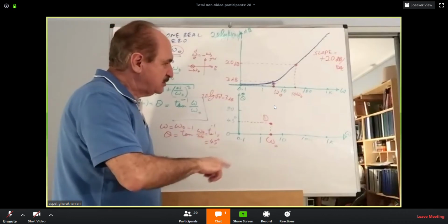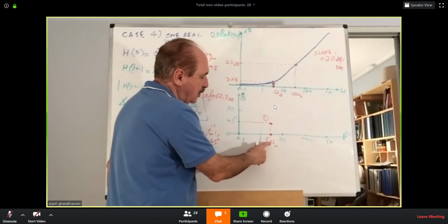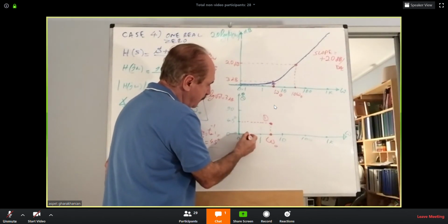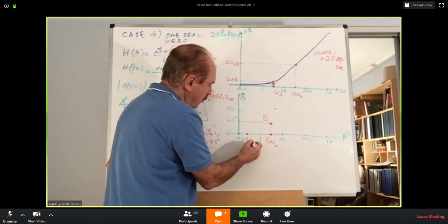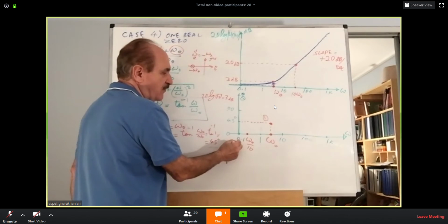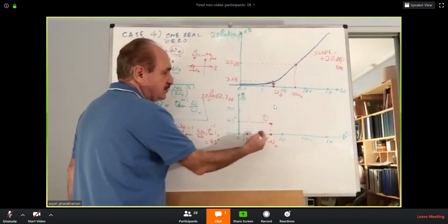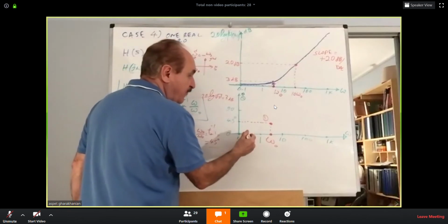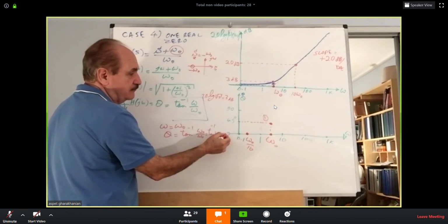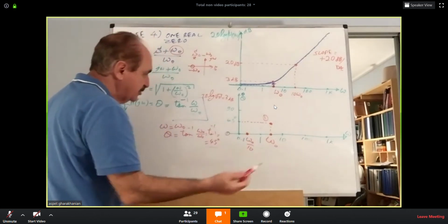Then go a tenth down, a tenth of this frequency. So 1/10 of omega O is going to be symmetrically here, omega O over 10, in the lower scale of 0.1, 1 to 10, 10 to 100. So they go up in decades, they divide in decades. So find that point. Level it with the 0 degrees. Now, why are we spotting that point as 0 degrees? Here is the reason.